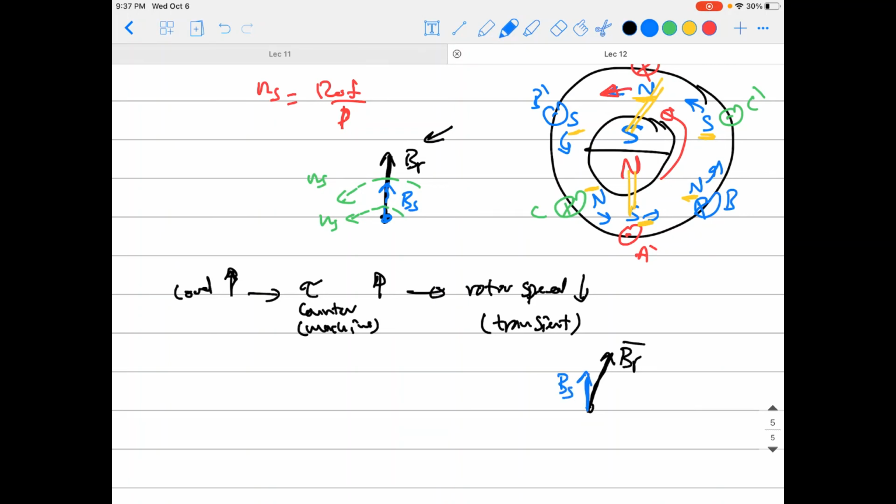Why? Because the rotor is the thing that slows down, because it's a mechanical brake acting on the rotor. It's not about the field of the stator. The field of the stator is just coming by electric current moving in the winding, so it doesn't have any means to slow down. Okay, so those will keep rotating at the same speed, but now you have an angle between them.